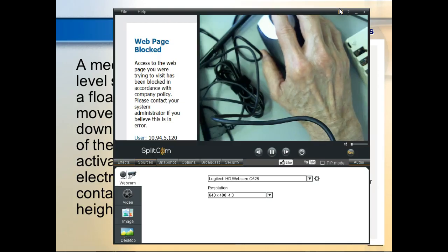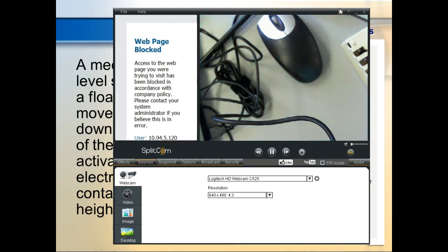Now, the Harley Davidson motorcycle has what we call a dead man switch. Anybody ride a motorcycle where you switch it between the reserve and you don't actually have two tanks? What you've got is a wall in there that it fills up, and then when it drops down and gets on the second side, you're supposed to switch it when it starts sputtering on you. So you're leaned over in a curve trying to reach between your legs. And then what do you forget to do? You forget to change the valve back, you fill your tank up, and then you run out of gas, right? Because you don't get the sputter. Has that ever happened to you?